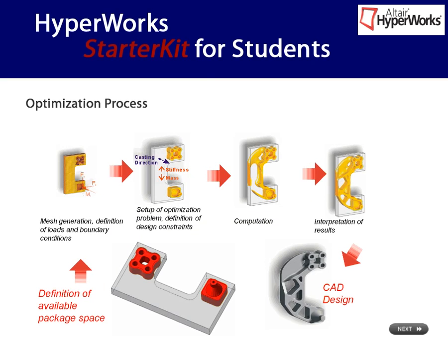What does the optimization process look like? In fact, the process is rather straightforward, as you typically begin with a rather rough first CAD model. At that point, do not think too much about internal structures such as ribs, holes and so on. Just pay attention to the outer contour of the component, which essentially is restricted by packaging requirements. However, this first rough CAD model may contain areas or design details which shall not be changed during the optimization